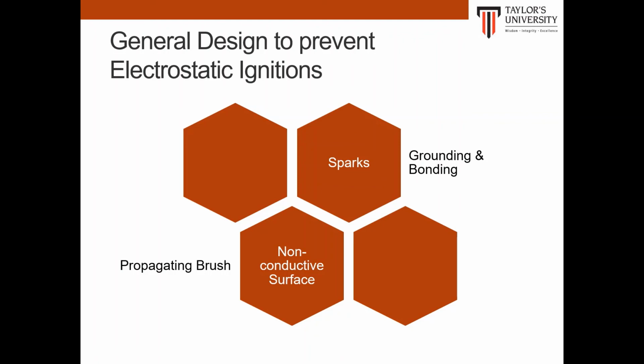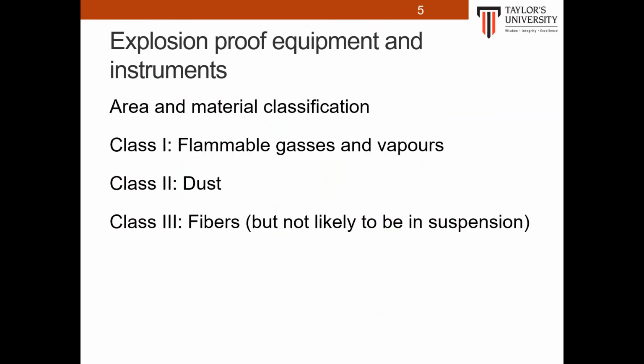There are also other discharge methods that you can study on your own, such as the cone pile discharge, the brush discharge method, or even what they call the lightning-like discharge method, which is prevented by keeping the vessel volume less than a certain amount. All electrical devices are inherent ignition sources. Special design features are required to prevent the ignition of flammable vapor and dust. The fire and explosion hazard is directly proportional to the number and type of electrical power devices in the process area.